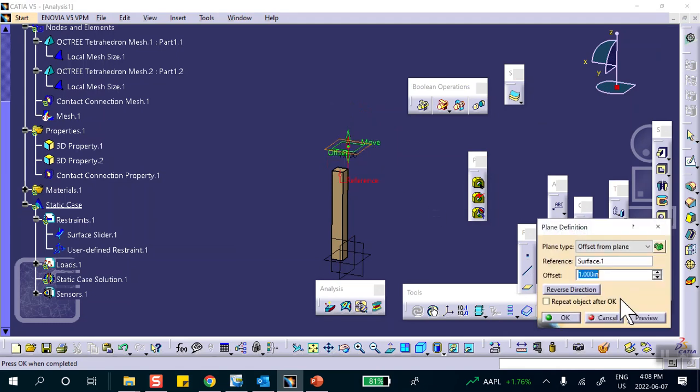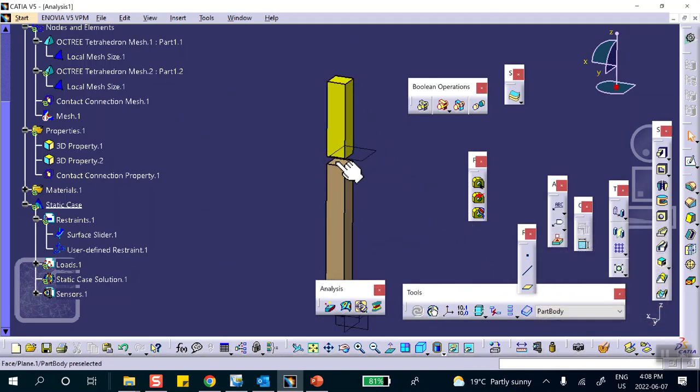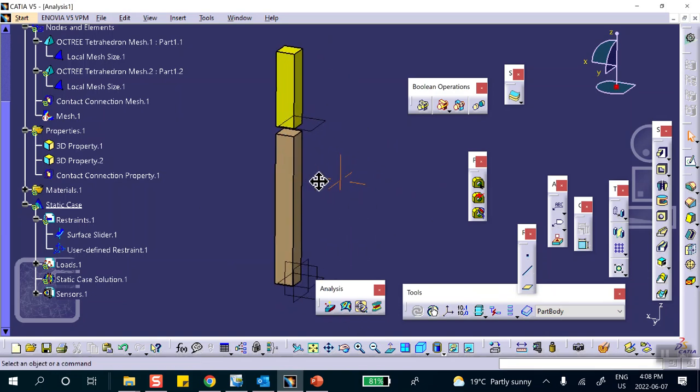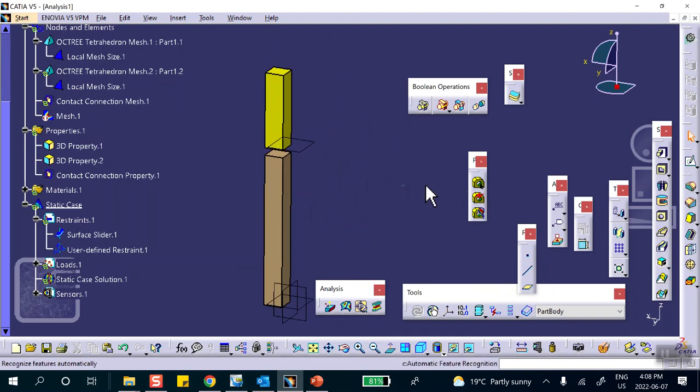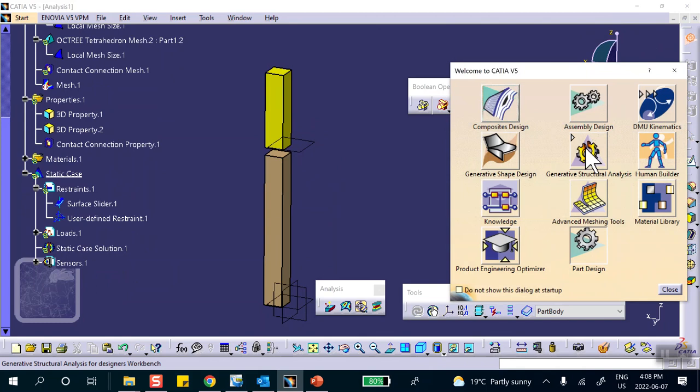And instead of the distance being 1 inch from that top flat surface, I'm going to make it 0.2. Okay, so I'm going to bring it down. In principle, if we move this thing by 0.25, it will actually establish contact. So let's first go back to the analysis and see if it runs this time.